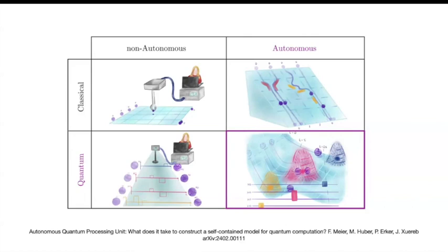But a superconducting qubit needs a very well-controlled environment, and one introduces these cables that bring extra noise. And so this is actually detrimental. Also, one cannot put thousands of cables into these fridges, because this would ruin the fridge, and there's physically not enough space. This is mitigated by multiplexing these channels, but it is something that limits the amount of qubits one can put on one of these chips in one of these fridges.